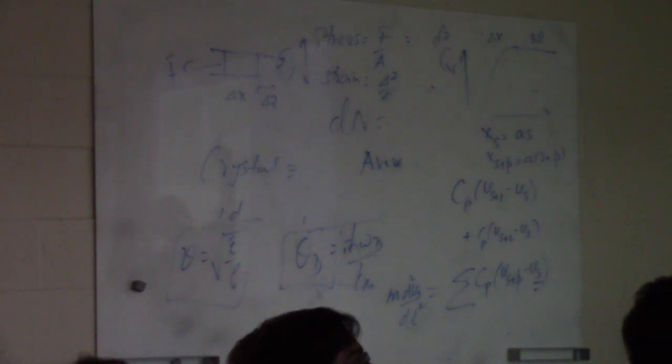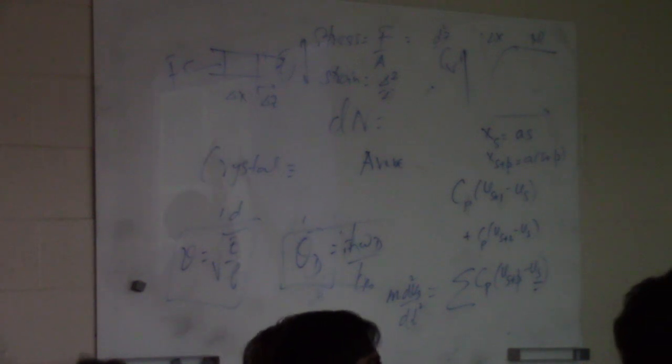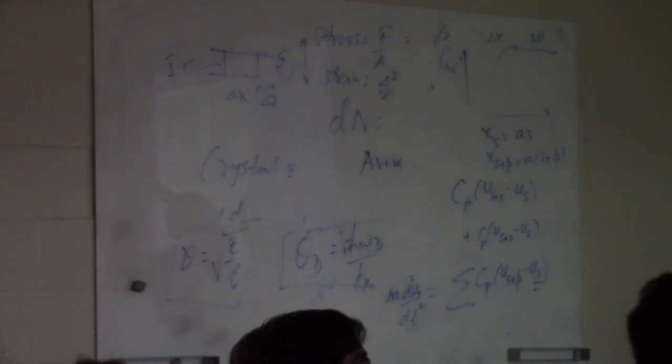But if you look at this aluminum 1, 0, 0 direction. Remember, we talk about directions, right? 1, 0, 0 means in this case, these two directions are pretty much the same, right? They are degenerate. So that means you will only see one longitudinal and one transverse wave.